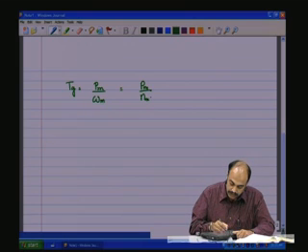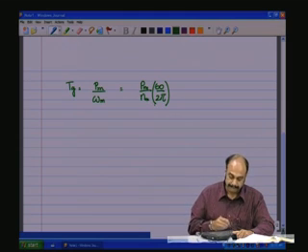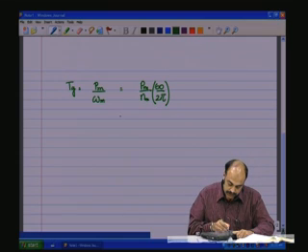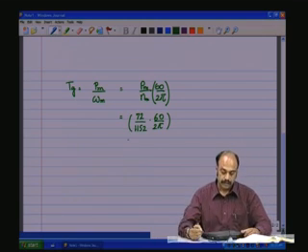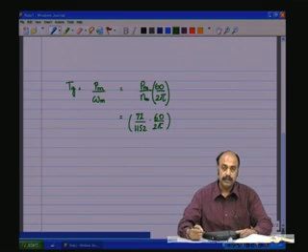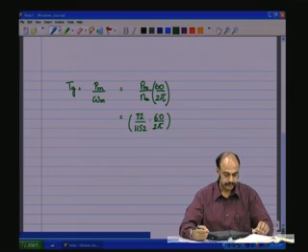To convert it into radians per second, we have into 60 by 2 pi. So in this case, we have PM as 72, NM as 1152 into 60 by 2 pi. So this is the generated torque, the mechanical torque at the mechanical shaft.